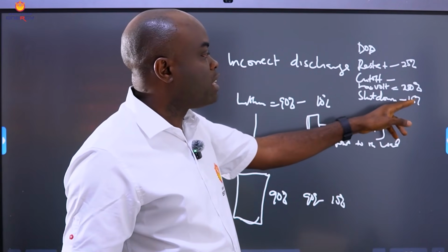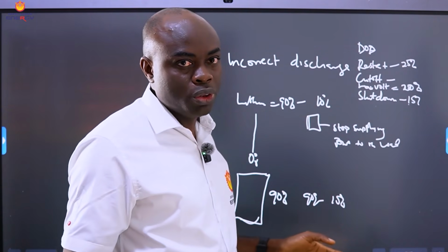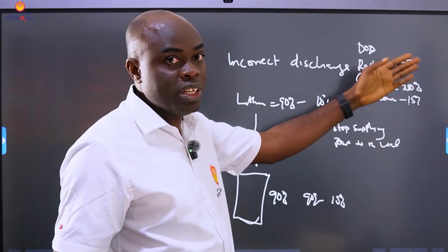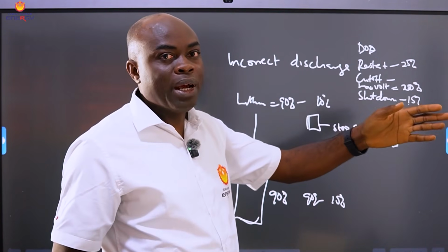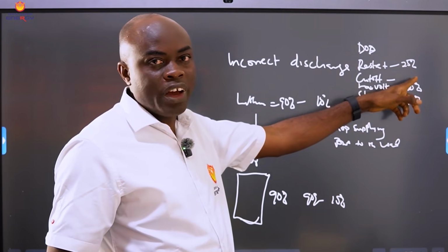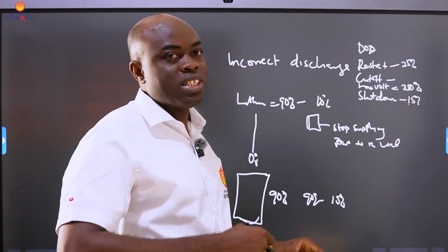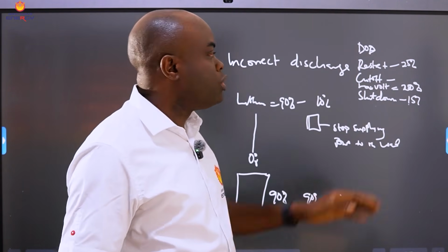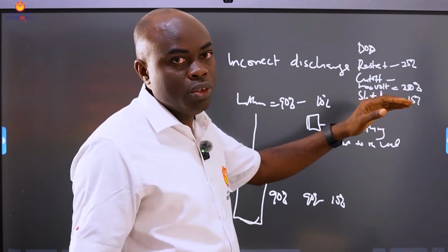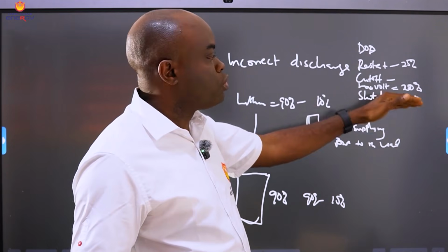So when the grid goes off, for example, and your battery is 20%, your load will be cut off. You will now be wondering, why is it that my battery is already above the 15% cut off, it's 20%, so the inverter should start powering my load? It's because there's a command on it: restart at 25%. It means that when the battery has not reached 25%, don't send power from the battery until it reaches that 25%. When it reaches it, and for example the grid goes off, then your battery can still power your load. Then it can now drop also to 15%.